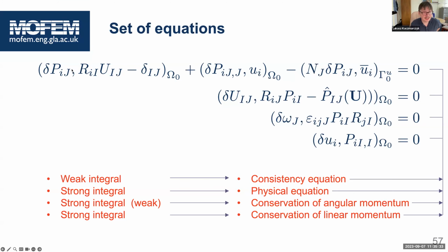So this consistency equation I write over here, but in order for everything to work, I have to add more equations to solve my problem. I have to add the equation that my approximated Piola stress is equal to the Piola stress, which I calculate using stretch. Because I have the stretch, I can calculate the Piola stress, which comes from my constitutive equation, whether it's Neo-Hookean, Kirchhoff-Saint Venant, Hencky, whatever it is.